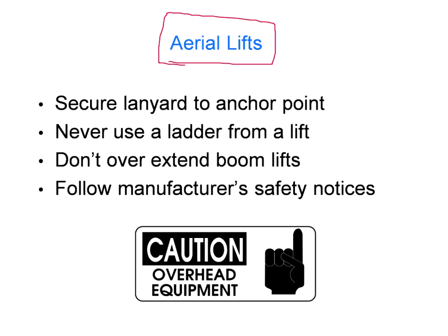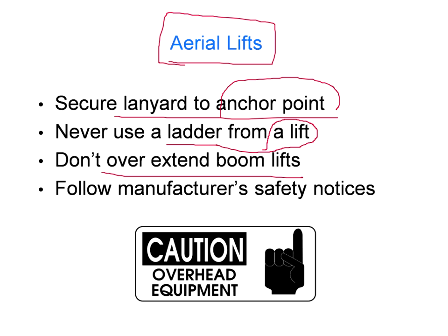Next is aerial lifts. Aerial lifts, secure the lanyard to an anchor point. This also uses the anchors. Never use a ladder from a lift. Don't use a ladder when you're already in a lift. This is a dangerous situation. Avoid this. Don't overextend boom lifts.